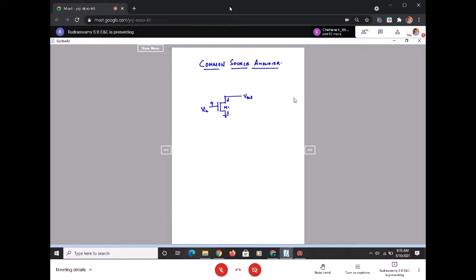And I said the disadvantage of having a passive resistor is that it occupies more area on an IC. Because it's all about small scale transistor integration, it is not preferable to have the passive resistor. So instead of the passive, we would go with an active device. That's why we used a PMOS where gate and drain are shorted, so it becomes a diode kind of connection as a load. We are replacing a passive load with an active load.